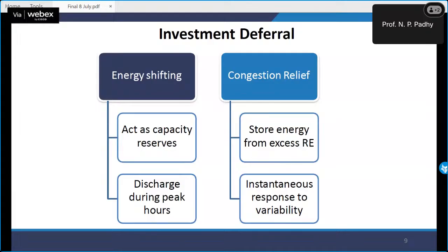You see what is happening today: to maintain the consumers, where the load keeps on oscillating, I need to procure the peak energy from the exchange. But that's not a good optimal solution, because only 2 to 3 hours you have to consume full energy, and the rest of the time you have to pay, because if the peak is 100, off peak is 50.